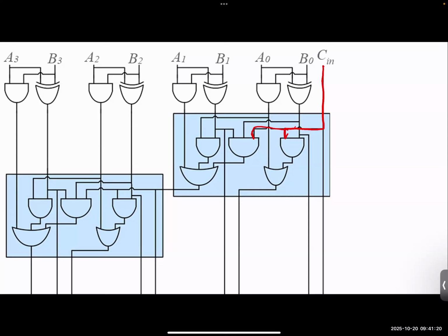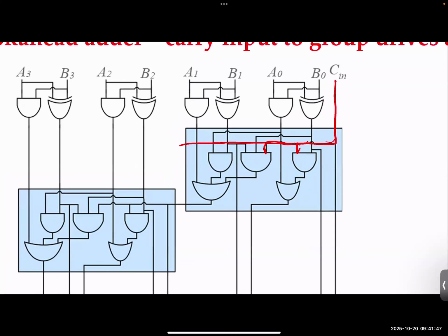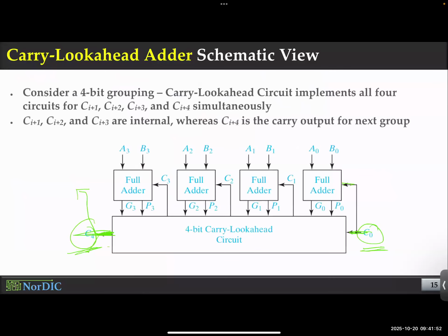Okay, quick question. If I try to incorporate 4-bit look ahead logic, so this is a 2-bit look ahead logic. We just look ahead 2 carries at a time, not more than that. If I do 4-bit look ahead, how many branches will this carry in deal with? Help me understand. How many? So every carry that you calculate, you need to provide this carry input, right? So let's go back here. These equations will help you understand.